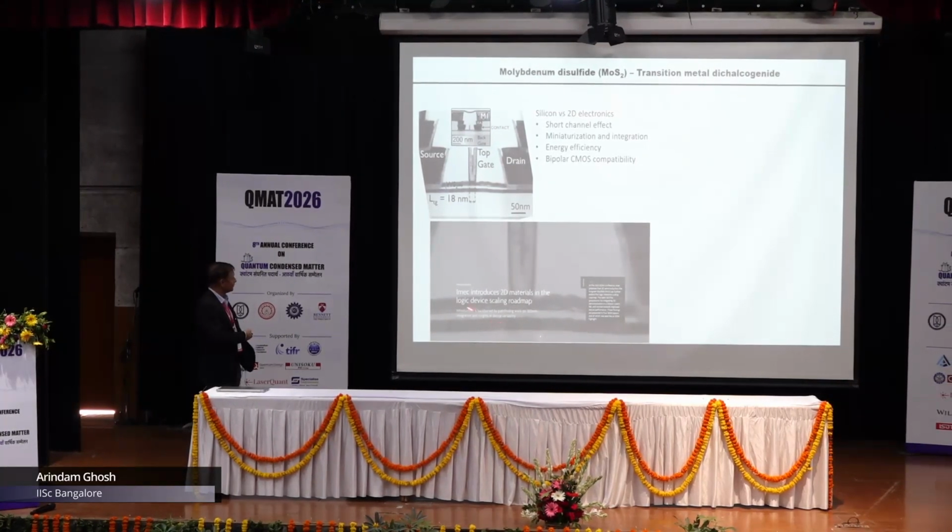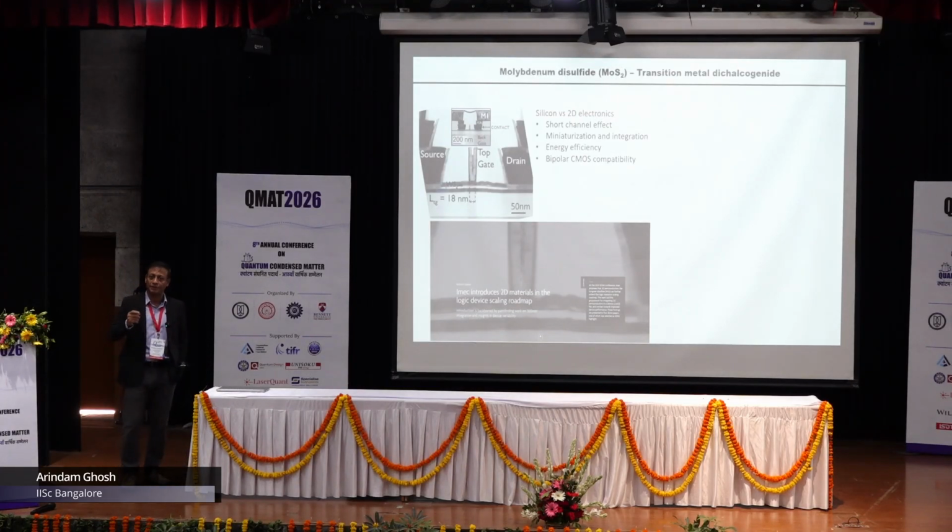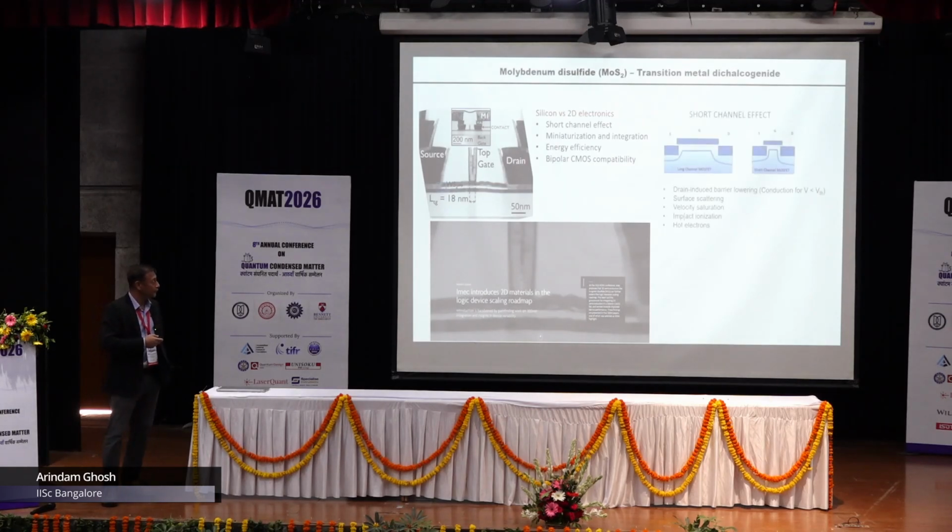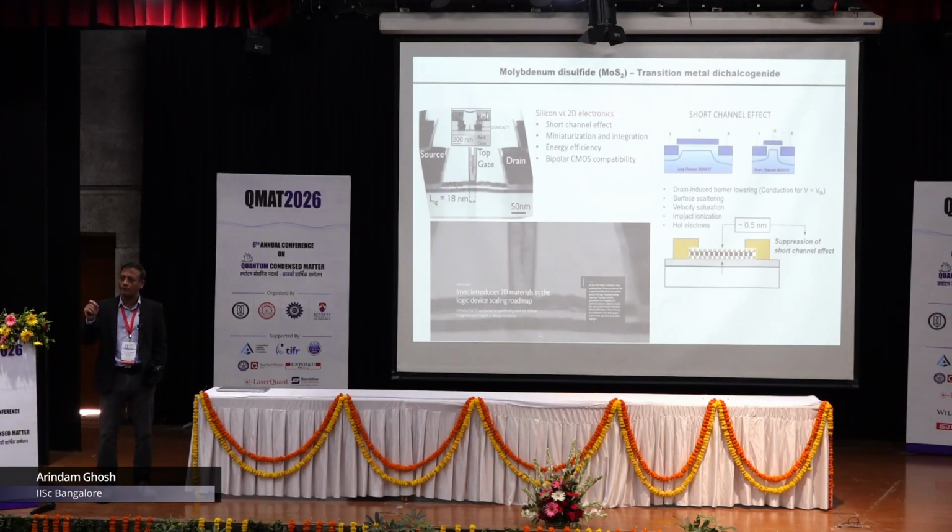Now, in the case of molybdenum disulfide, because of its semiconducting properties at an extremely small scale, you have a serious application possibility in electronics. Certain key bottlenecks of conventional electronics can be sorted out. One perfect example is the short channel effect. Usually, as you make smaller and smaller electronic devices, where the source and the drain come closer and closer, applying a source voltage usually decreases the barrier properties.